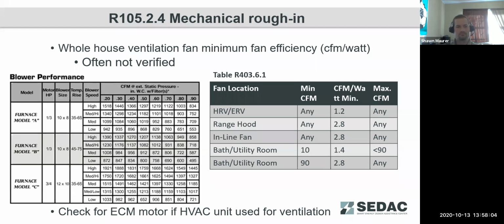You can see blower performance changes based on the static pressure across that fan. So it's important to check and make sure that that fan static pressure matches the airflow requirement. It's not uncommon to see installations where you've got kinked ductwork due to installation practices that will reduce that airflow and thus not meet the intended design. So it's important to check and make sure that that is correct during that site inspection.